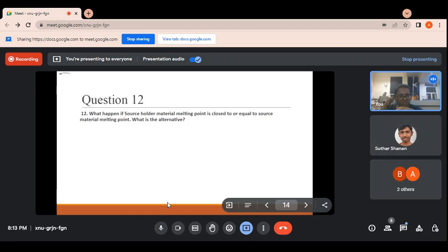Then we go for the etching process. But only for SU8, it is discussed in the lecture video that we go for the soft bake at 65 degrees centigrade, then we go for the hard bake process, which is 90 degrees centigrade.